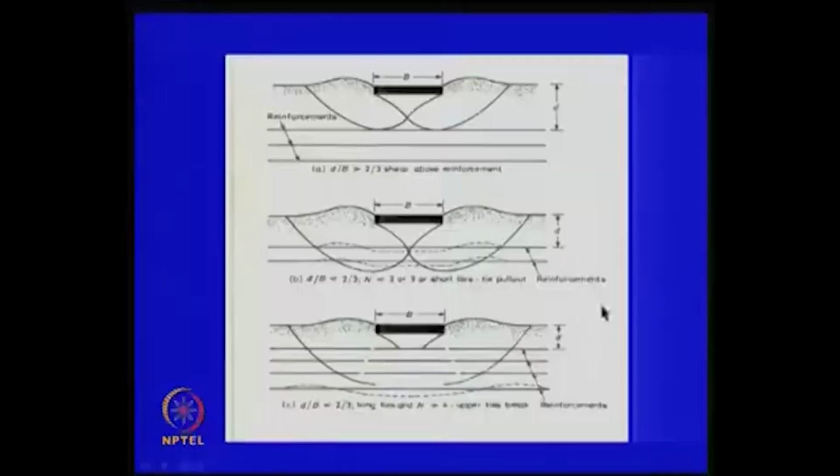If the length is not adequate, it may not really develop frictional resistance completely, and even if the friction is developed, it should be able to sustain that friction by pull out resistance. That is the reason I said the factor of safety, there is always a relationship between the pull out resistance and the tensile force developed.